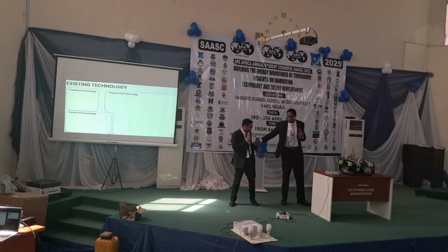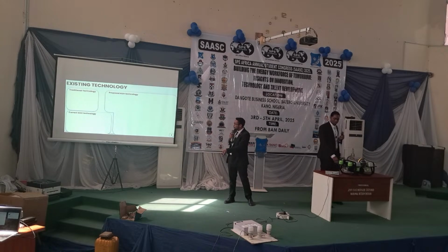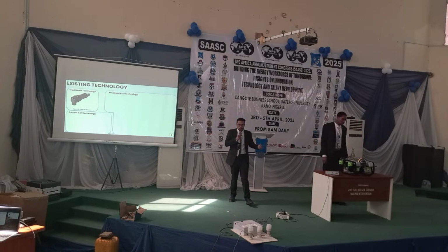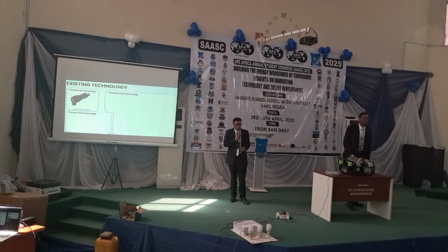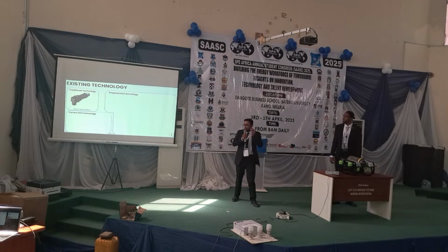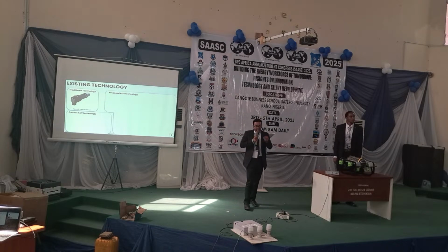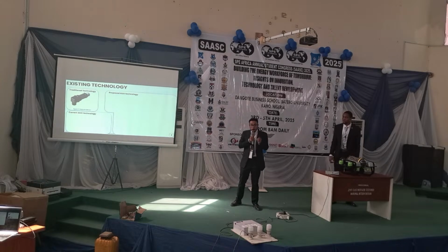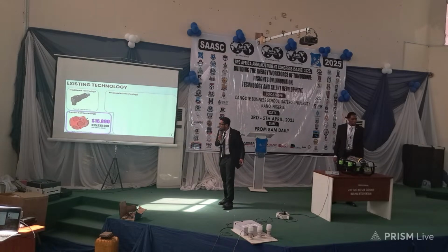Pipeline leak detection has been done before. Traditionally, we use pressure sensors, and as demonstrated in this event, these pressure sensors are placed at intervals in the pipeline. When pressure fluctuates erratically, it indicates that there is a leak at a certain interval within that pipeline. But the fundamental problem with this is that the exact leak location is undefined. For onshore pipelines, we use numerous methods of finding leak location. But for offshore pipelines, autonomous underwater vehicles are used.